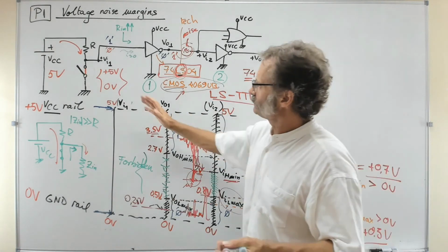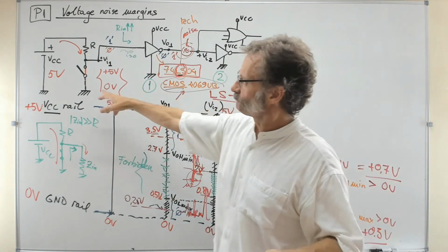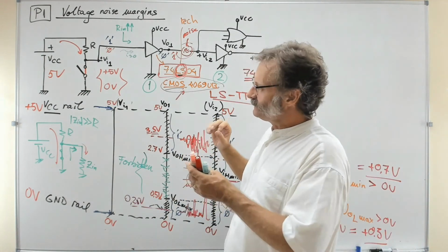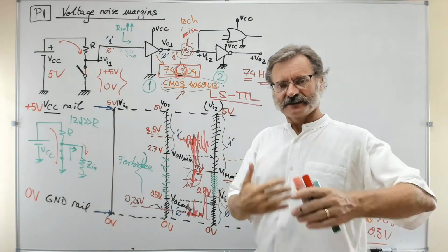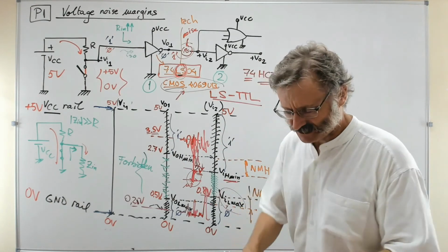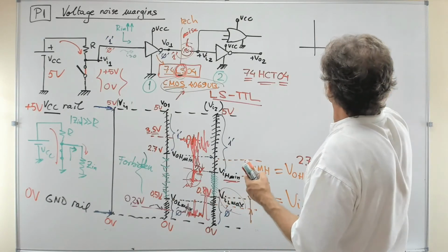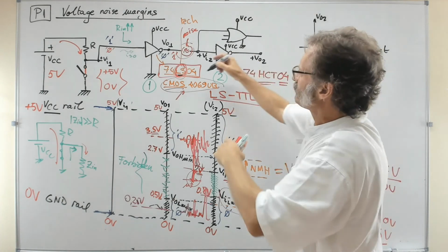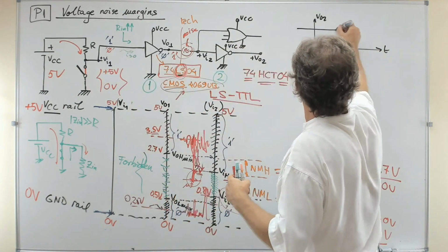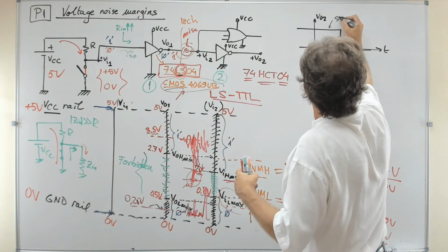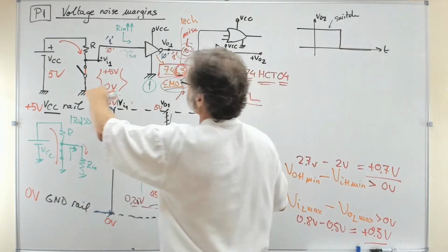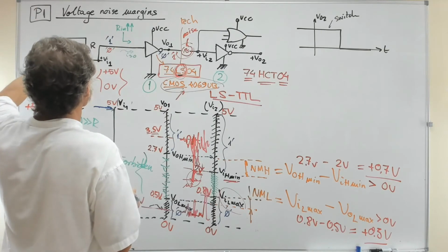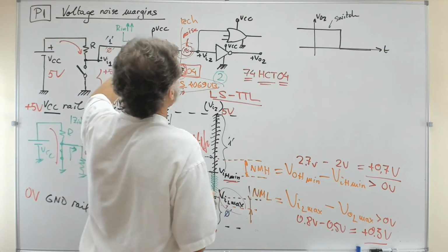And so that is the typical circuit attached to a real push button. Later we will improve that again, because there is going to be the idea of debouncing the signal, because I can advance you that the signal is not going to be that clear. If you imagine now that in time, this is, for example, V02, which is the same as V1, you may say that it is like that. This is the switch: when the switch is off, you have a 1, then a 0, and so again a 1.